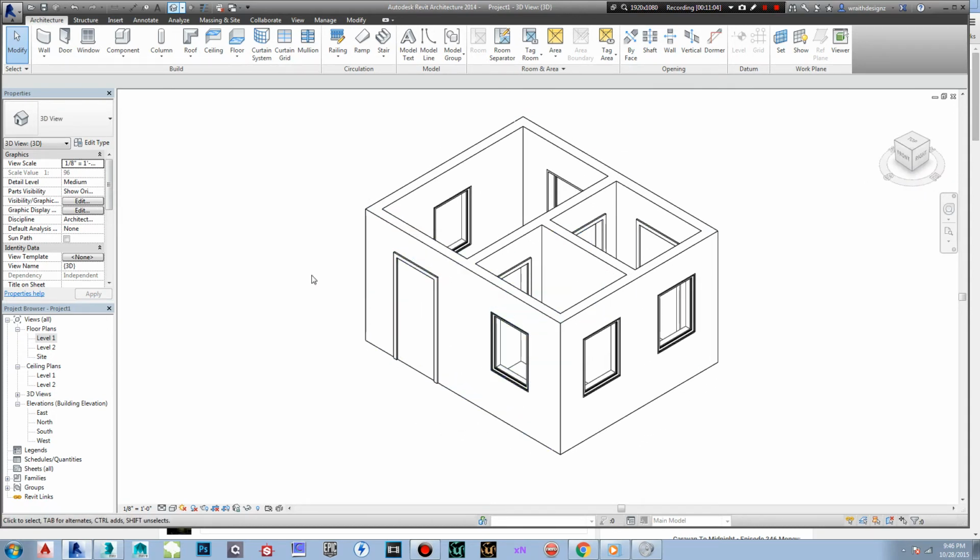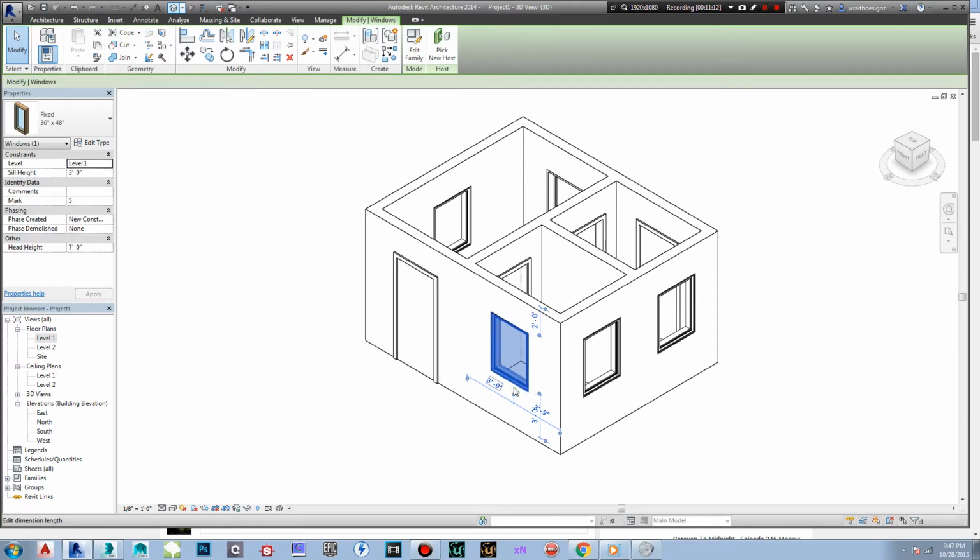So anyway, we're going to basically show you the little components of each window and door. I'm going to show the measurements, height, width, from one wall to another wall, things like that. When you highlight different things, it will tell you different information, like the dimensions of the window. So here we've got fixed, okay? I just had this already selected, so it's a fixed window. Obviously, it's not the same size. It is more square. That's okay.